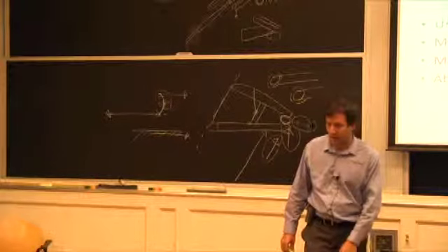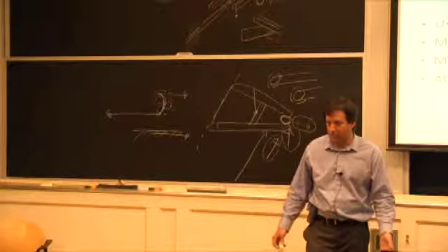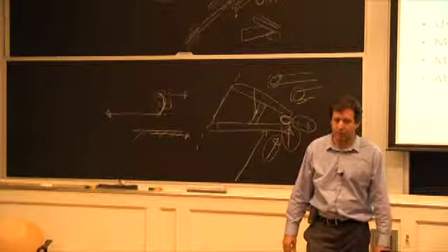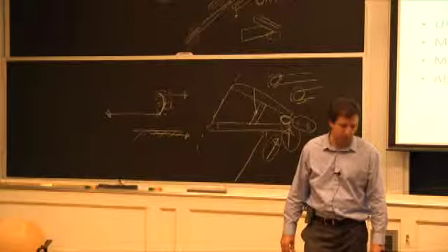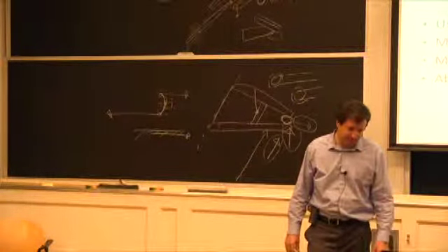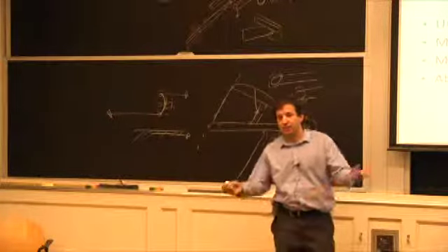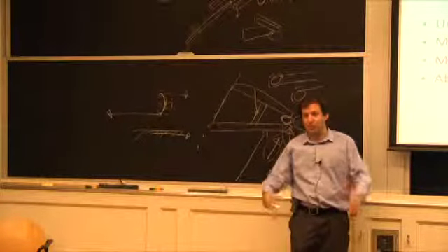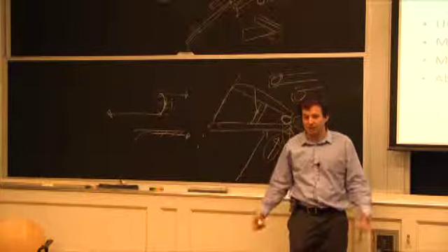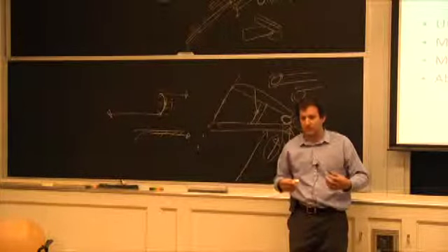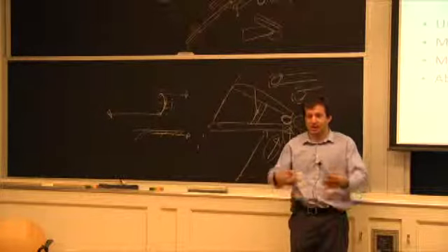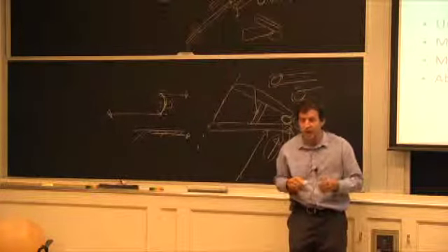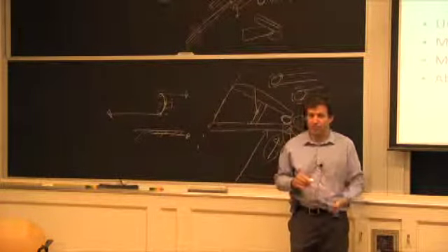I worked on the erection of big structural frames for nuclear recovery systems, and the contractor came and put in some tubing, just conduits for the electrical, into the main frame that had to be resistant to seismic deformation. So the design of the member was to work in plasticity back and forth. And if you have holes in it, it's not the same.